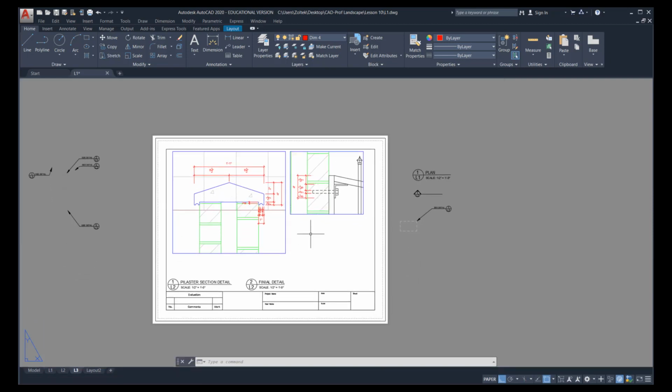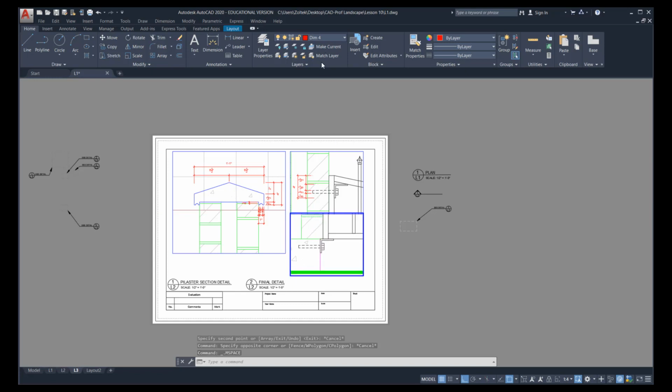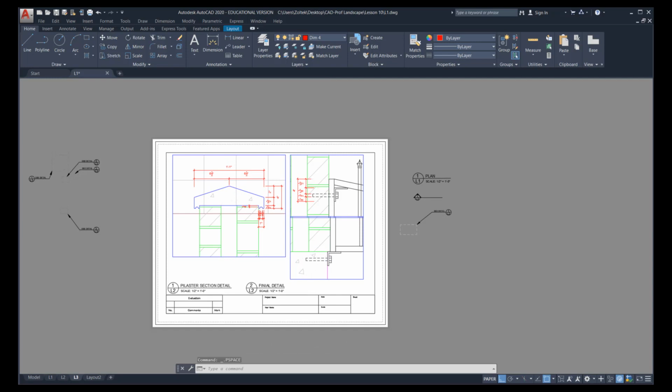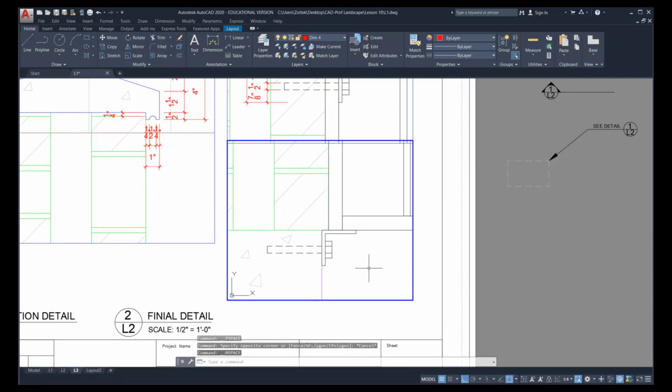Now let's make the second one. This one's simple. I can copy the viewport straight down, just giving myself a little bit of room for the title reference. Now I'm going to slide that bolt up, double click outside, roll my wheel, zoom in on the page, double click inside. I could have copied those sets of dimensions. I will do my lower linear dimensions first. There's my 4-inch.